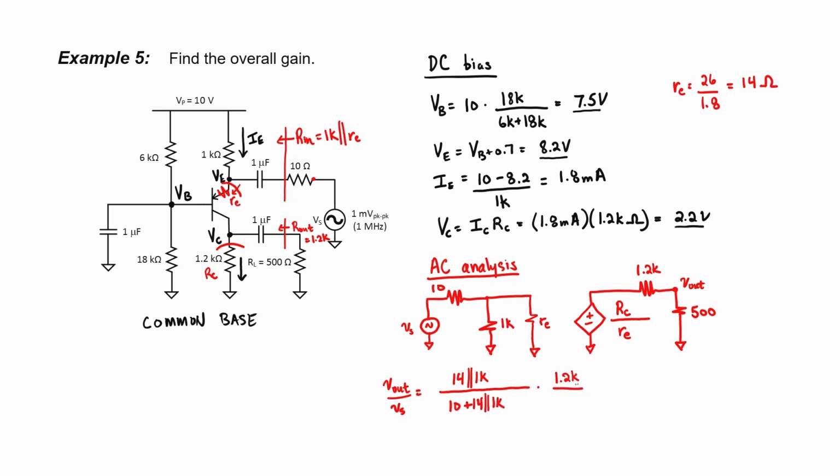We then have a very large gain here at the diamond, and then we have an output voltage divider as well. We'll use about half of our signal at the input side. We definitely make up for it with the large gain, and then we lose some of our signal again at the output side. But overall, the gain is a very reasonable value in this particular example.